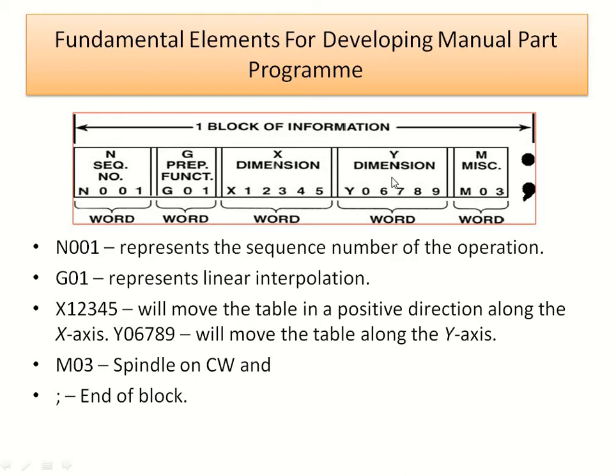The third, X and Y, will move the table in the positive direction along the x-axis and along the y-axis. The next word, M03, represents spindle on clockwise, and the last, a semicolon, represents the end of block, that is the end of the first block of information.